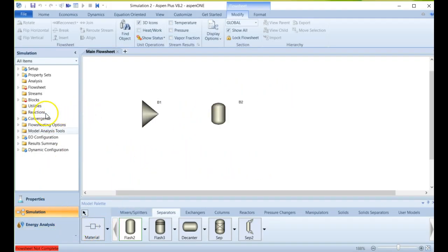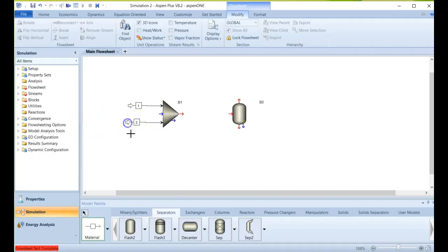In this case, we're going to create 2 streams, and I'm going to click and drag and move this up so it's easier to see. That's the 1st stream in. We can click and drag and move this out. Oops. There we go. That's the 2nd stream. And then we can click and drag to connect those. Connect. And remember, we're always clicking the reds for those connections. These little blue ones here are not of interest to us. These are the decant streams. So we can click that.